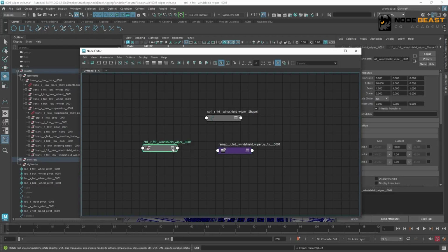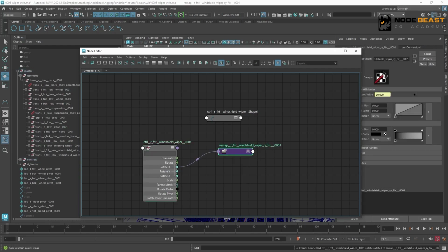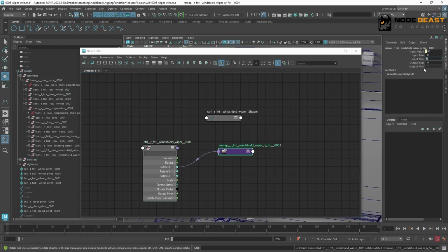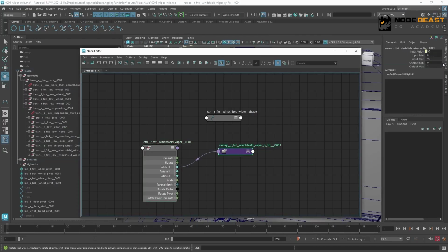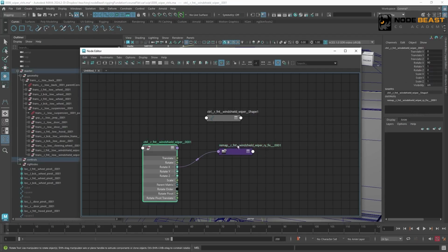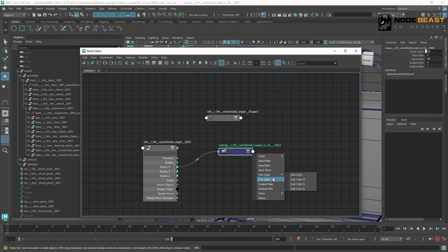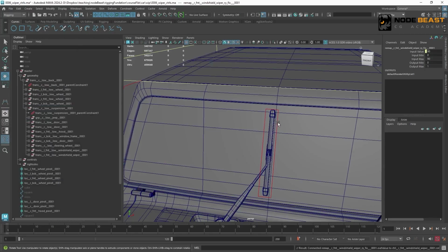We'll use rotate x to drive it. We saw this range is 0 to 90 degrees. And the range we're modifying is 1 degree. So the output here is 0 to 1. So when we rotate to 90 degrees, the final effect is 1 degree. Then connect this 1 degree value back to rotate y. This way, let's check again.